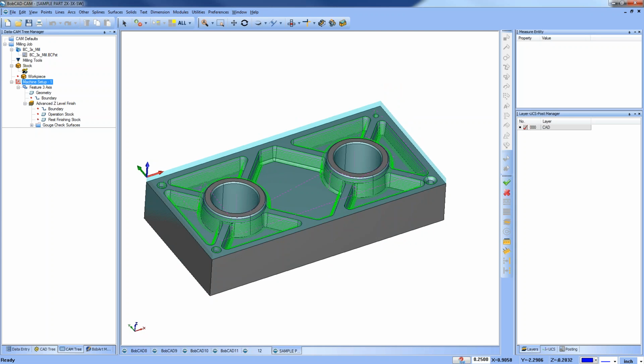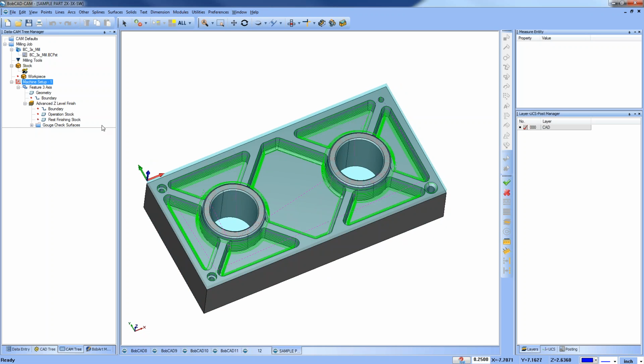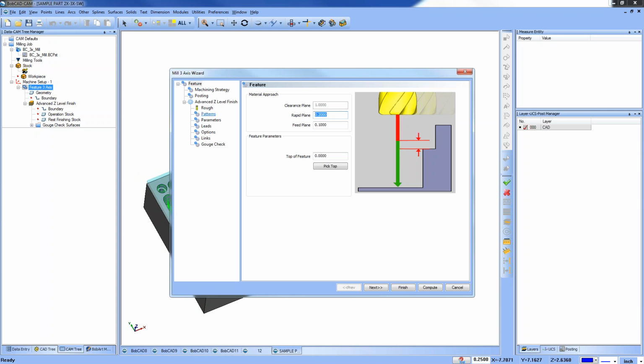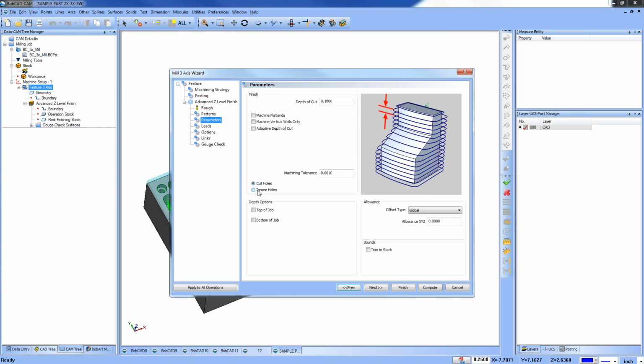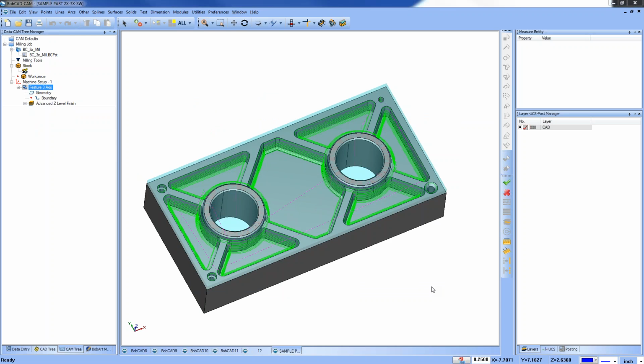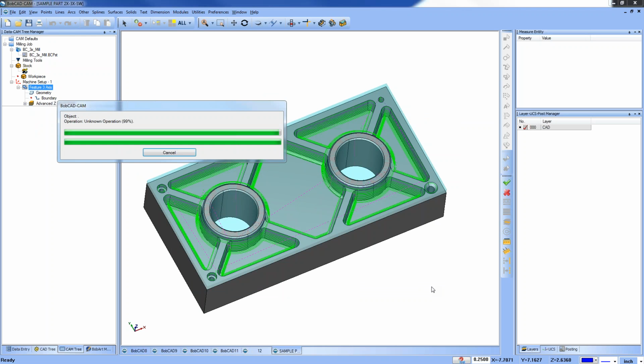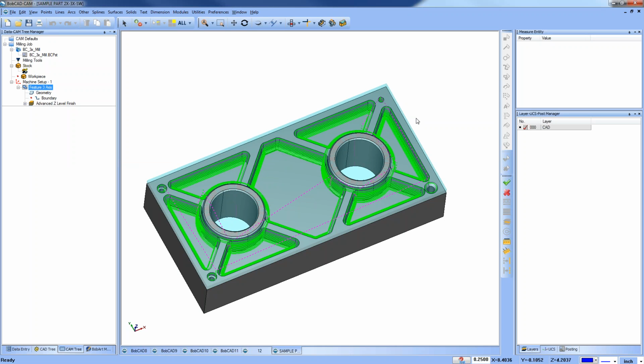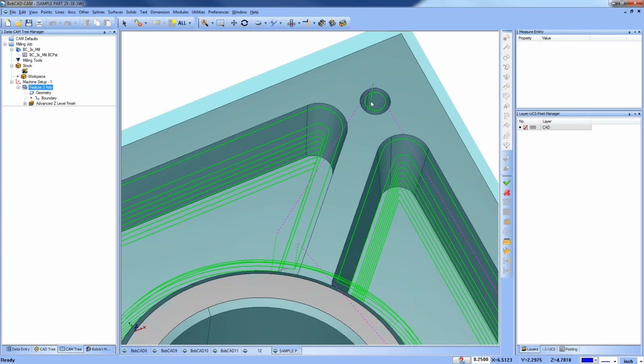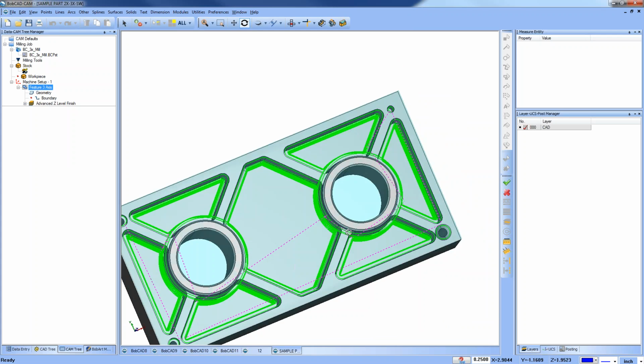But here you can see with the Z-level finish, there's some holes here. We might need to cap these surfaces. I've talked about this before with some of the 3D toolpaths. You'll see an option that says ignore holes. So I'll turn that on and recompute it. Sometimes that will ignore your holes. Your hole geometry has to meet a specific geometric condition. If it doesn't, then it's not going to read that as hole geometry. And that's what you'll see here, you can see how it wasn't able to read those as holes.